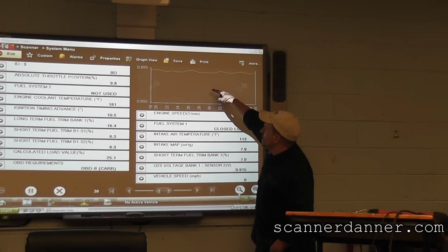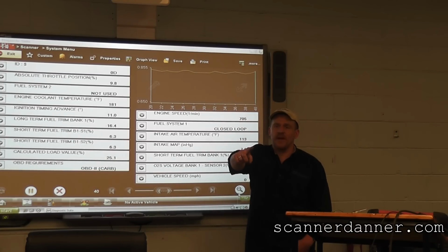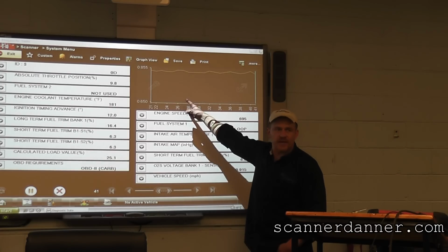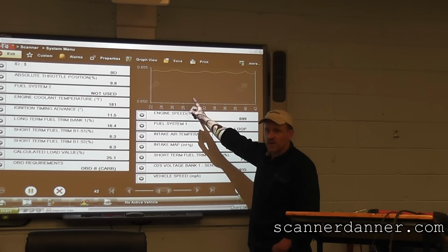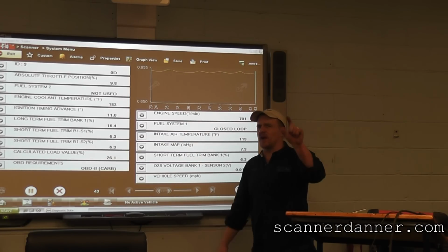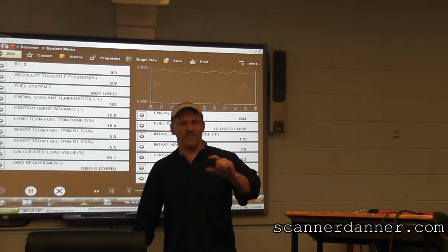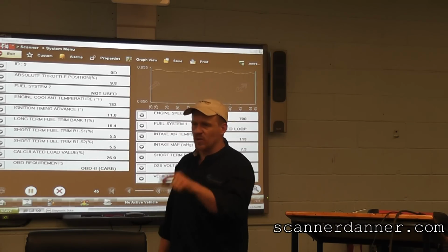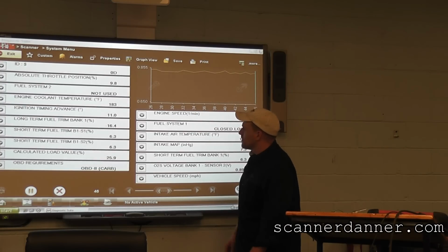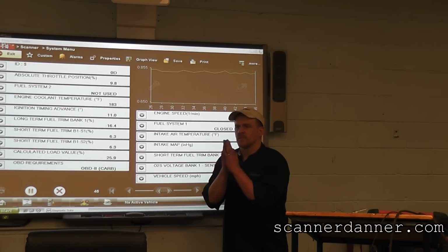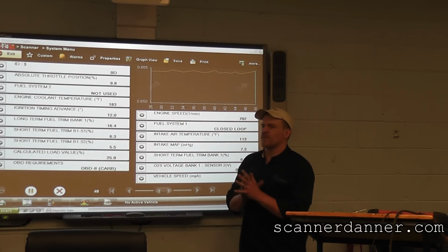This upstream one, we want to see this thing fluctuate, but I believe this is a wideband and this is a calculated number, and I don't think you're going to see the same kind of fluctuations on this vehicle, because under the factory data it said AF. When you see AF sensor, AFS, that's an air fuel sensor, that's a wideband, and I don't think we're going to see the same rich lean we've been talking about. What kind of volt reference do they want on the widebands? Is it 5 or 3? Like 3.3 volts on the ones that I've measured.